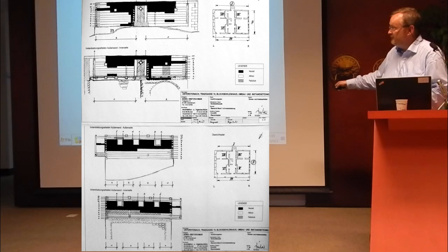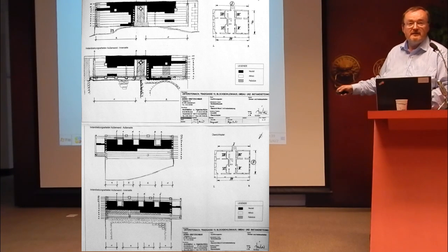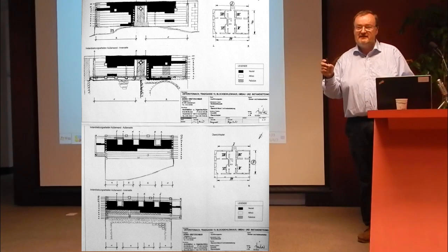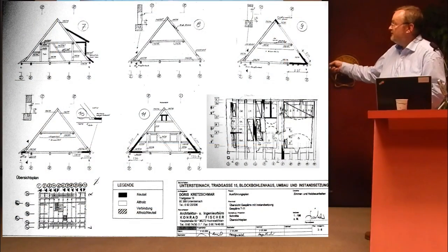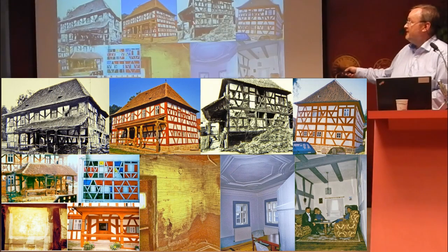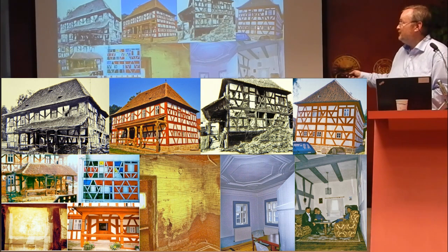Another wooden house with a lot of damage, you see, but we make it also very clear, wall for wall, what is rotten, what is okay. So we must do planning very exactly onto the last nail. Then we have a chance to make it in an economic way. Here's a whole little wooden building. All parts are documented. And then we have the possibility, the opportunity to repair a building, and it looks maybe never before or 300 years ago.